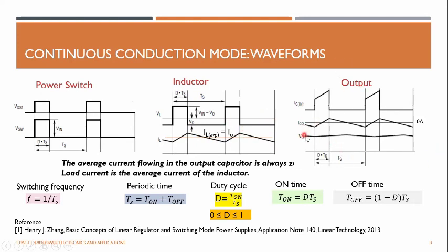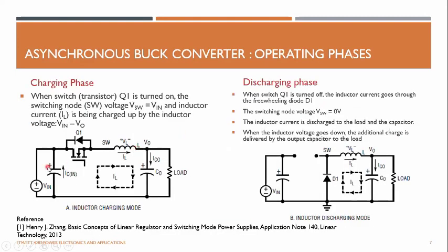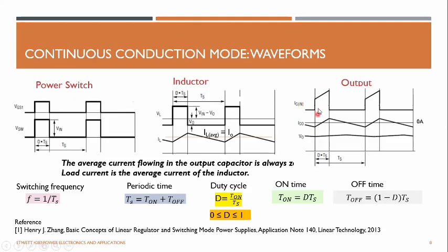And so you have this kind of peak to peak ripple at the output due to this switching. So this is the input power source, the battery current. When the device is turned on, the inductor current should be supplied from either this capacitor or from this battery. Assume there's no capacitor, which means the battery is providing this inductor current, right? That is this current.